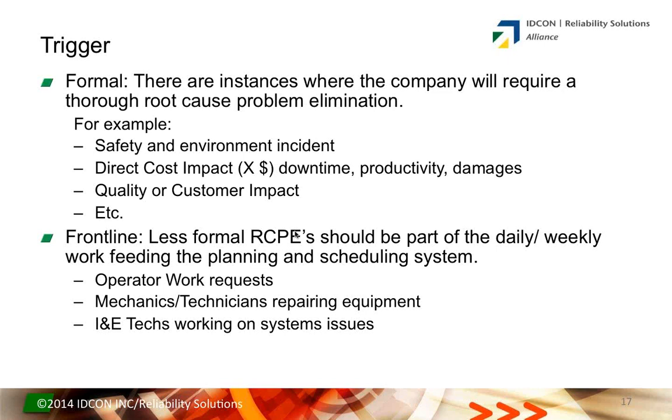We have become a generation of parts changes. Something breaks, we change the part. And what passes today for troubleshooting is often just a whole bunch of parts changing. I challenge each of you listening to go back to your facilities and look at how people, for example, troubleshoot hydraulic systems today. Typically, people are going to have a problem. They're going to maybe tweak a couple of pressure valves first, and if that doesn't work, they'll just start changing pumps. They'll change valve blocks. They'll change pieces without the troubleshooting.